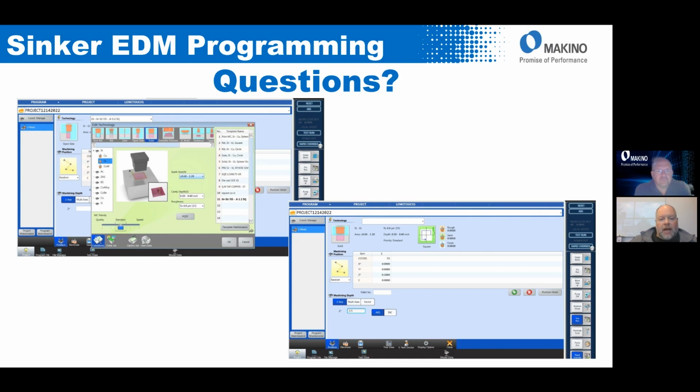So there's nothing the operator has to do. Really, all we're doing is putting in how many C-axis rotations or how many degrees based off of X amount of Z depth. So very simple. And then if it needs any kind of orbit with that setup as well. It's a very good section on the helical machining side. Any guys that do helical gear machining will truly understand the setup pages, and whether it's lead entry or module entry, how that setup is from the data they get off of a print. So it's designed very well for the guys that do helical gear machining, and they'd really understand at a high level. All right, very good.